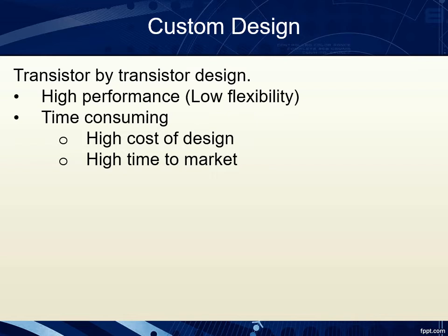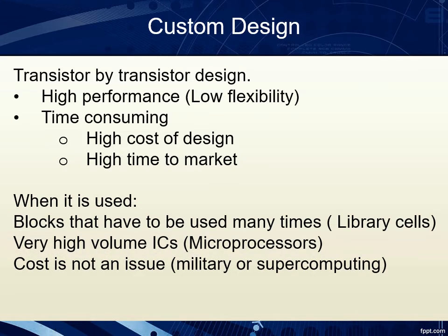There are few typical cases where a custom design is used. Custom design is always used for blocks that have to be used many times, such as standard cells or library cells. Very high volume ICs are also custom designed, for example, some parts of microprocessors.